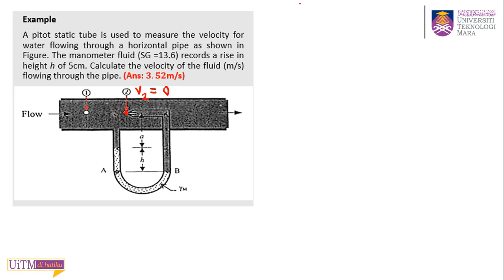Okay, now write your equation first. Continuity equation, A1 V1 equals A2 V2, so V1 equals A2 V2 over A1. Okay. Second one, your Bernoulli equation. Okay, what's the... my handwriting is bad. So what's the equation for Bernoulli? Can someone tell me? Your Bernoulli equation?